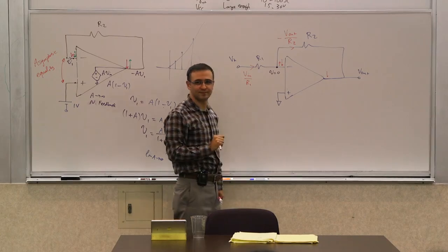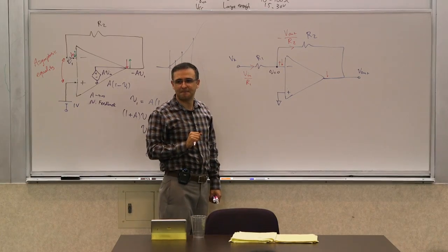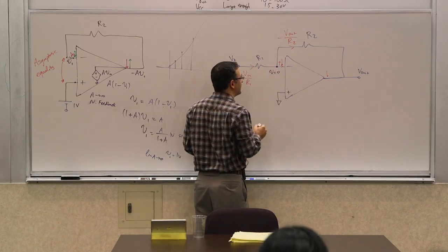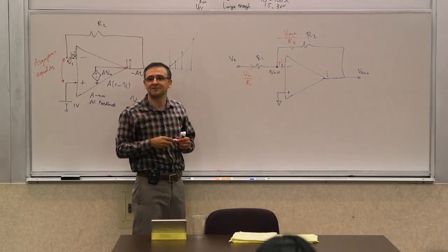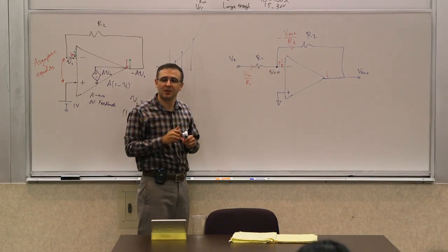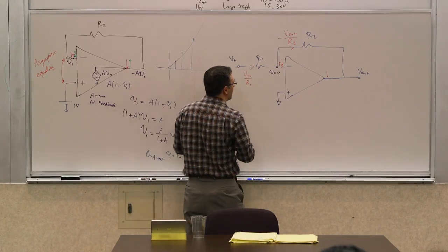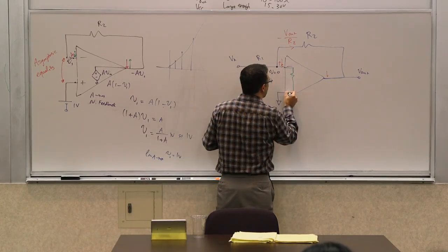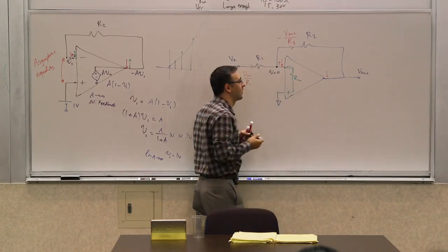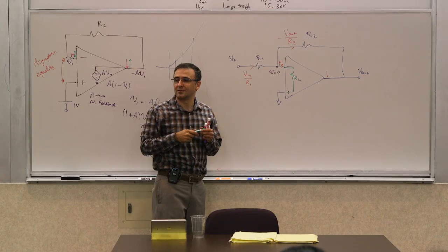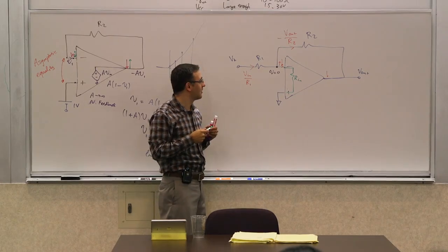Now, you said these two currents are equal. Why are they equal? How about this current? Why is it 0? Because we said that's infinite. Okay, what if the input impedance is not infinity? Let's say the op amp is not ideal in the sense that it has an R in. Would that current be non-zero? Yeah, it'd be non-zero, but if R1 and R2 are much smaller, then